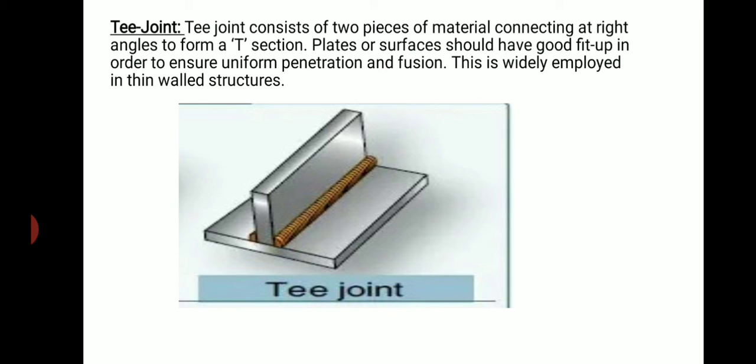Next, plate or surfaces should have good fit up in order to ensure uniform penetration and fusion. So the surfaces should have good fit up in order to have uniform penetration and fusion during welding. This is widely employed in thin walled structures.